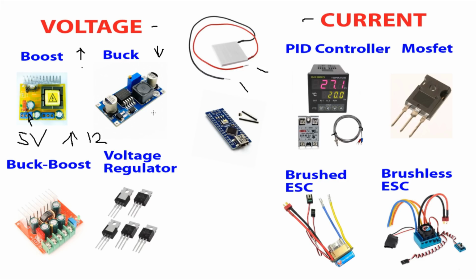So we've got a 12 volt power supply, we can reduce the voltage down to theoretically 0. However, an awful lot of controllers cannot actually reduce the voltage down to 0, so that's something to be aware of too. So you may not be able to adjust it and prevent any current from flowing in, slash voltage, or power if you like.